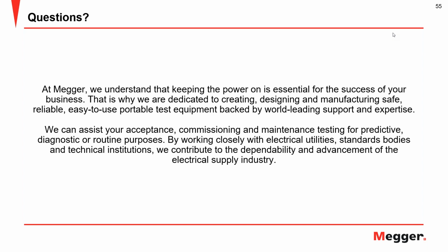You measure dielectric properties of the insulation, but in this case, which also contains these additives. So when you do a measurement on a brand new cable, whether it's XLP or EPR, your measurement will invariably be influenced by the dielectric behavior of these additives.